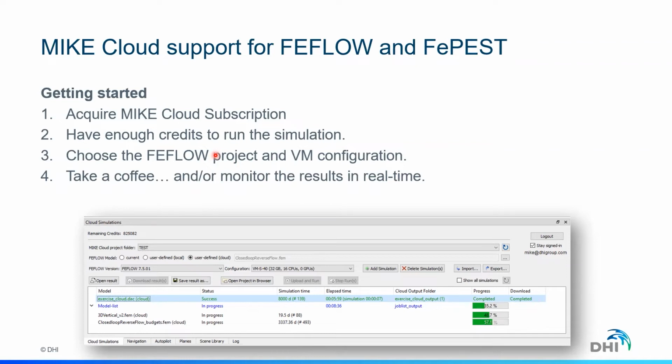In FEFLOW, you are used to looking at results in parallel during the run. So we also have a set of charts called cloud charts, where you can look from your desktop application at what is happening in terms of the time steps or hydraulic head to concentration values. So basically the different charts that we typically use in FEFLOW runs.